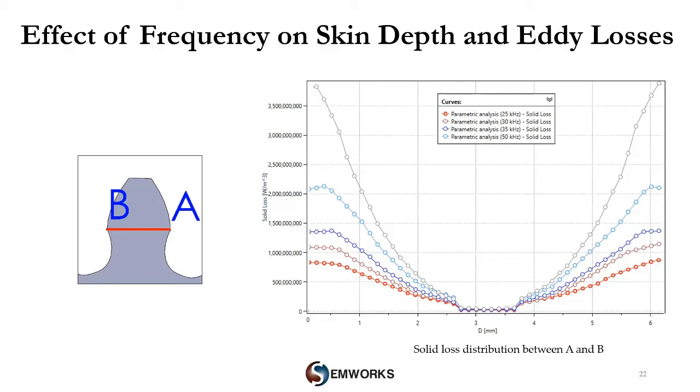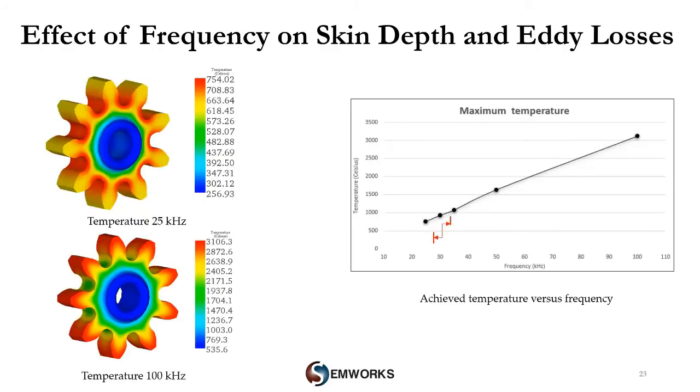Now, what about temperature results? Let's have a look at it since it will define the hardening rate. For the following temperature results, at the first and the final used frequency, we can conclude that lower frequencies are used to heat the gear root region, and higher frequencies are essentially used to heat the top teeth surfaces and at higher temperature values, which is essentially used for the dual frequency hardening type.